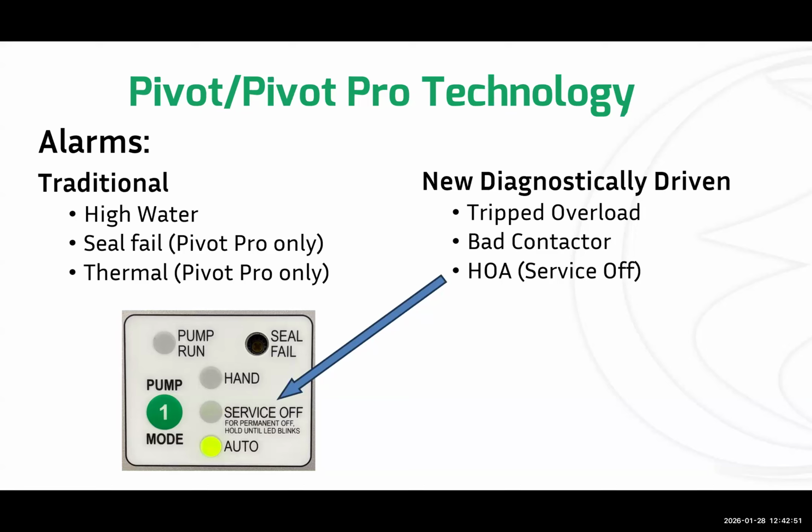And then, like always happens, something comes up. It's more challenging than I thought, or I have to do more at the project than I thought, or the day starts to get late. I'm tired, I'm hungry, I'm cold, I'm wet, whatever it might be. I finish up, I do my service work, and I'm ready to leave. And I walk back over and I close the control panel, I lock it all up, and I leave. And what I haven't done is taken the pumps out of off. So that's a problem, right?